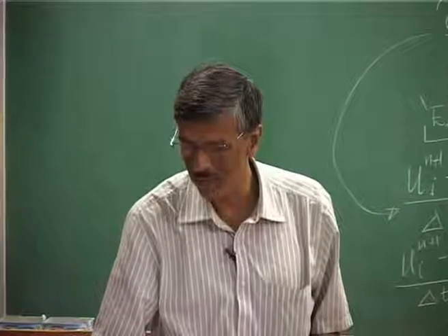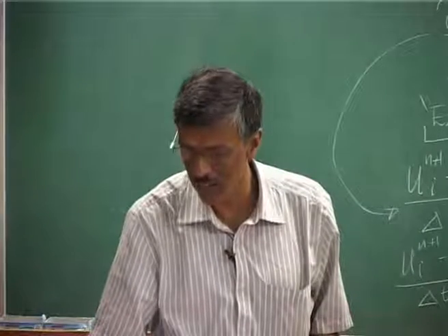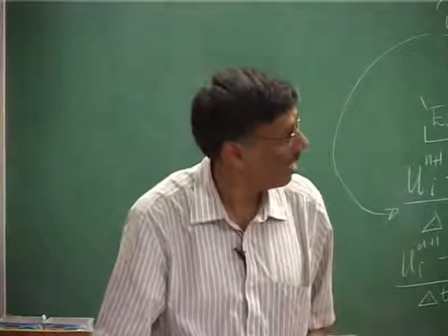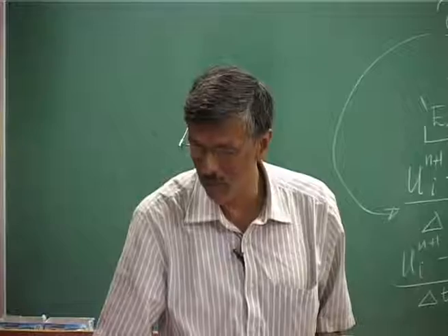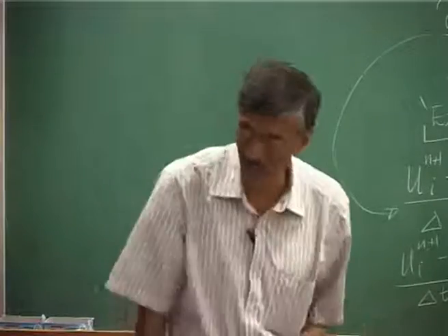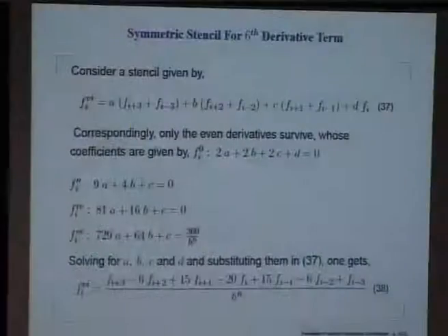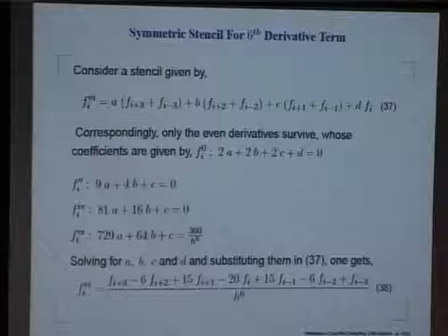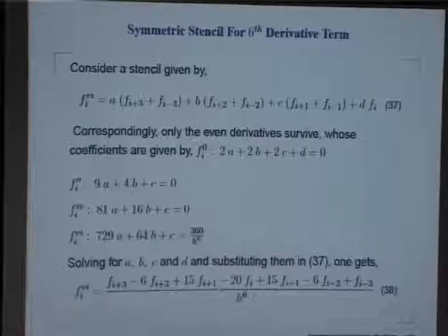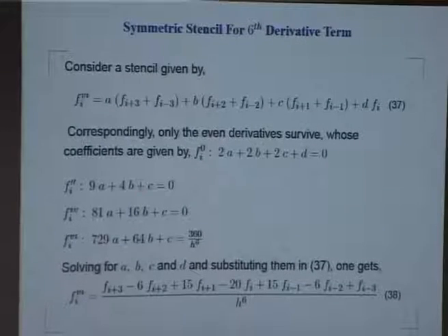See, we have first derived these 6th order accurate and 4th order accurate expressions for the first derivative, and now if I want to add a 5th order upwinding, what I would be doing is take that 6th order central difference scheme for the convection term, and to that I will add this 6th derivative term.